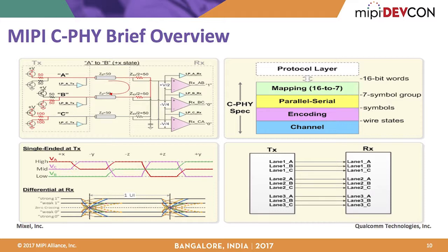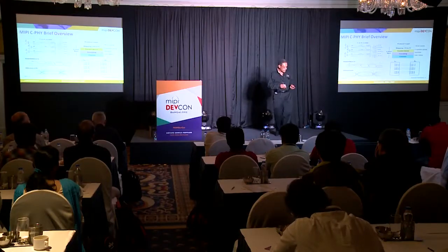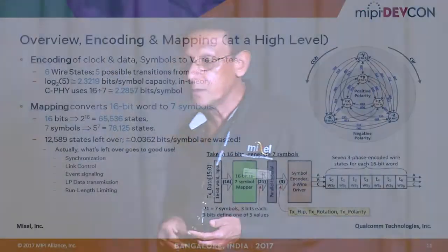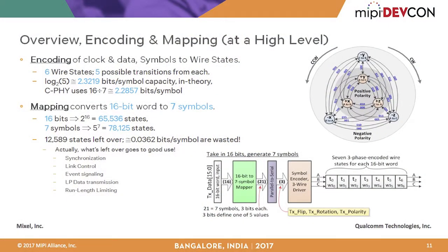And then a third function is that it ensures that the common mode voltage of the 3 signals is constant at the mid-range. So basically, you have 3 signals here that allow you 8 combinations. Some of those combinations are not allowed because of what we talked about. There are some restrictions.